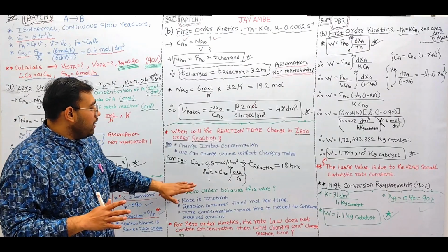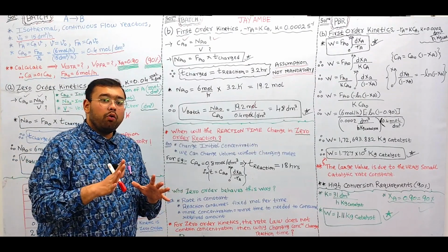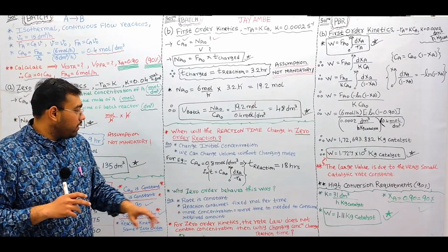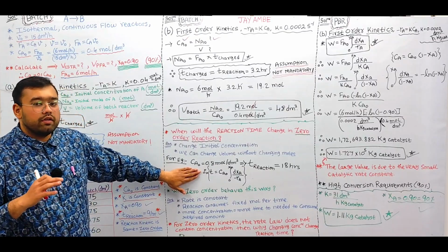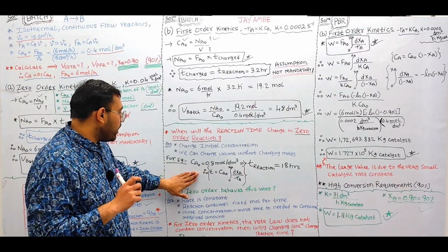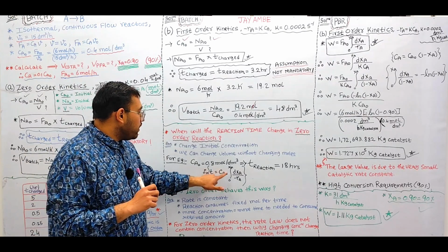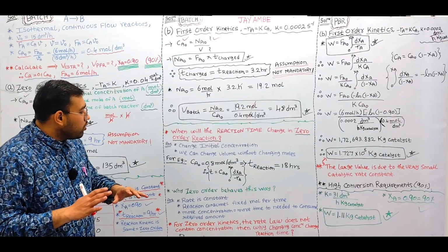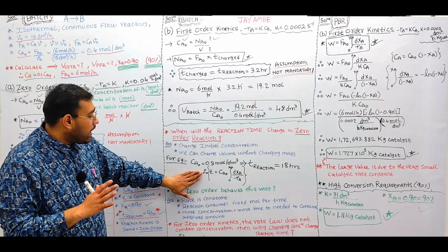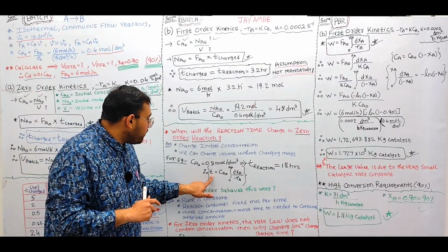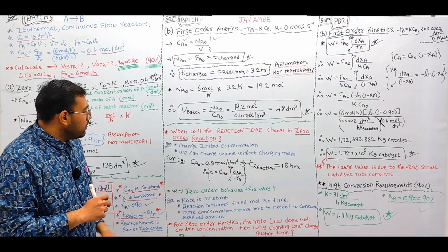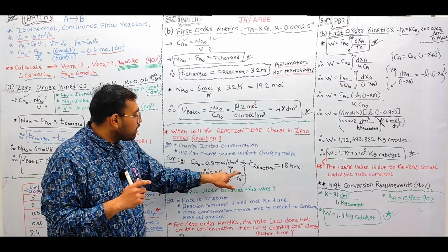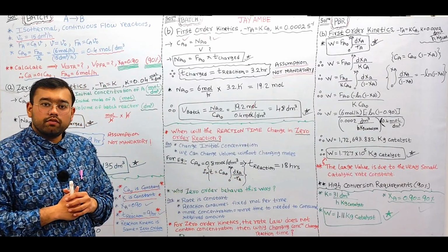So recall the fundamental concept of the batch reactor, the performance equation of the batch reactor. This formula represents the performance equation: T is equal to C naught integral from 0 to Xa of dXa upon minus Ra. Now observe and analyze that T represents the reaction time, so the reaction time is a function of concentration, conversion, and the rate of the reaction, right?